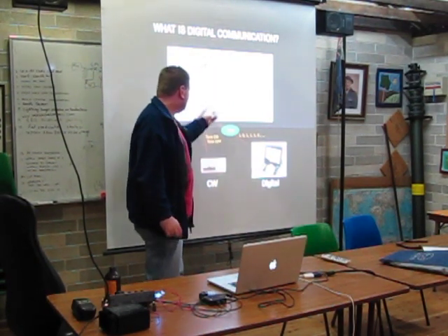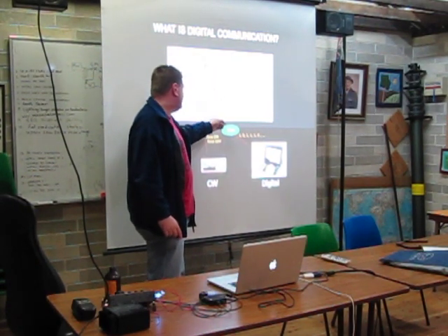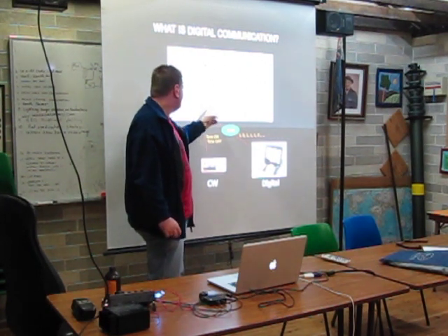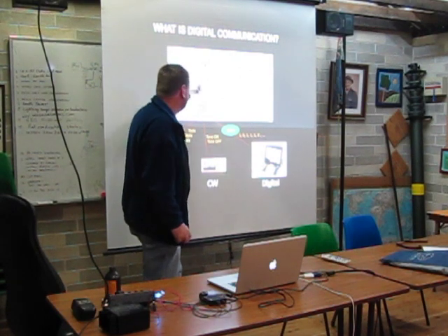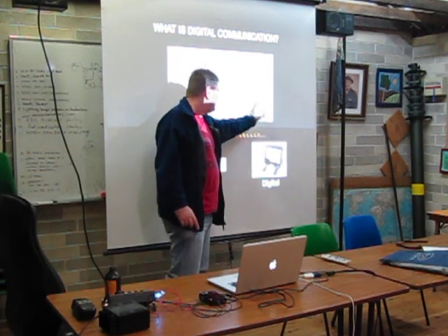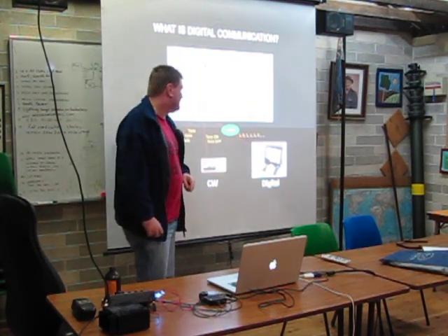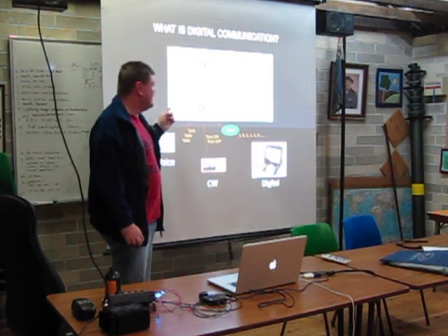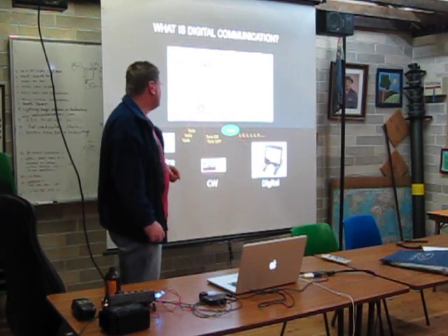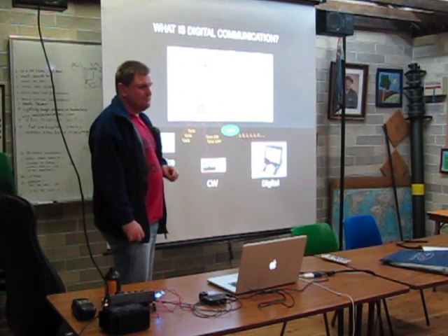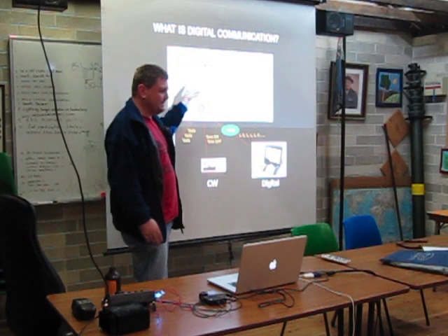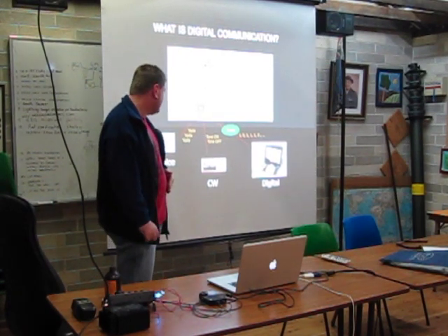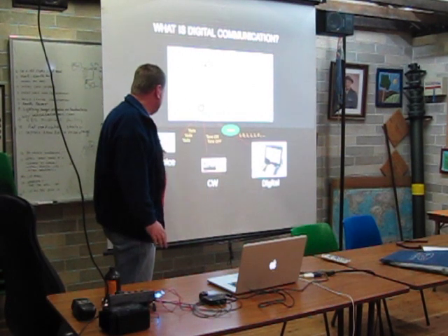Your audio voice would appear down in this part of the spectrum, in the audio frequencies. When we mix it with a carrier frequency, it gets shifted up into the radio frequency part of the spectrum. This is quite a simplified diagram of how a transmitter works. In practice, we often have a couple of stages; we don't normally go all the way in one go. But it works with voice.